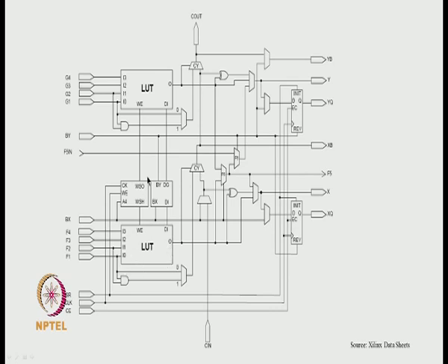Okay, suppose you have an FPGA, 50% of the lookup table is not used as logic, and you have used all the memory, the block RAM, as a memory, and you want a little more memory. But if you look at it, a lot of lookup tables are lying around and they are memories, but you cannot use them because the write circuit is not available to the user. So what Xilinx or other FPGA vendors do is that the write circuitry is made available to the user.